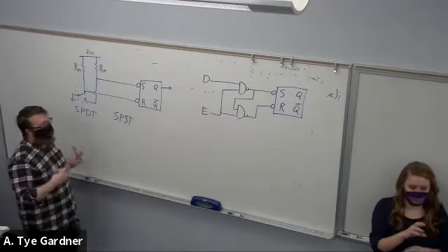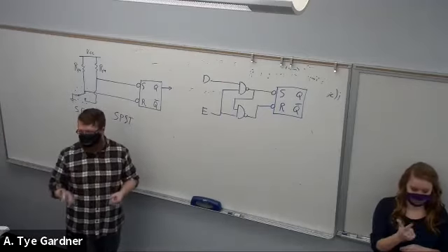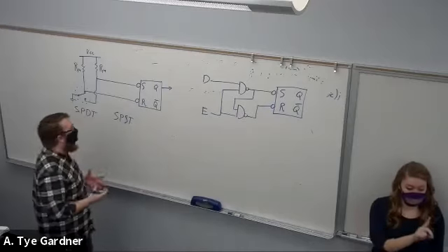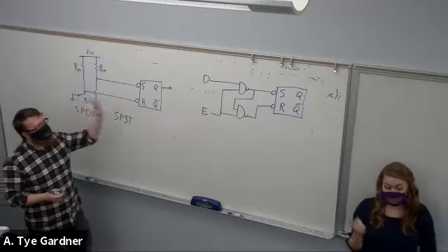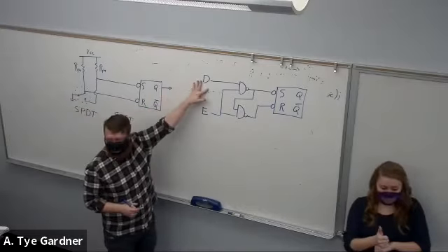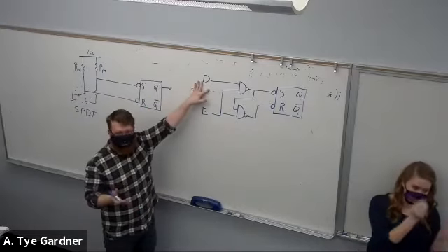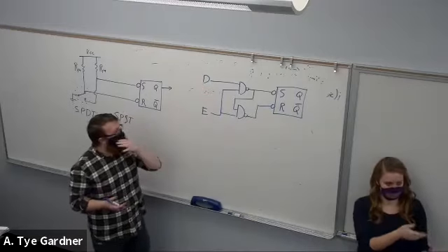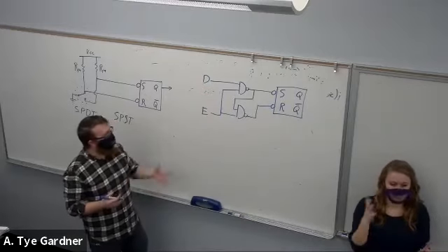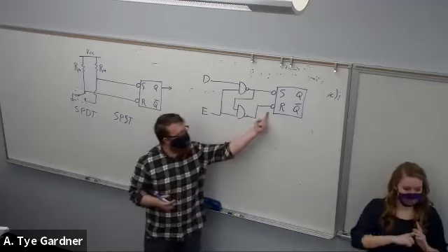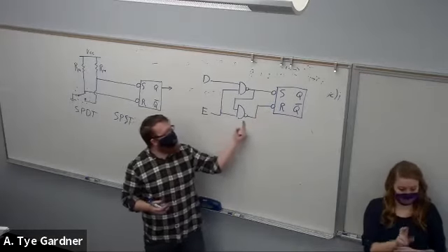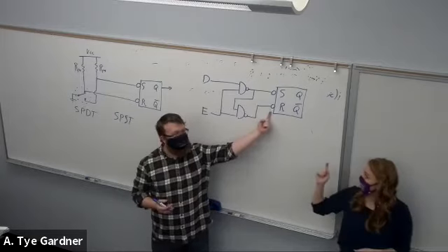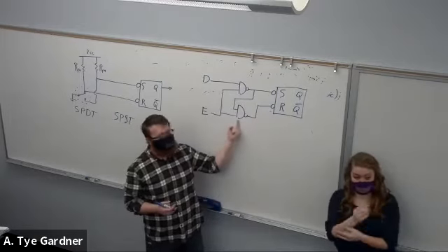So this is what we call a D-latch or data latch. So rather than having the options to set or reset, we can actually take a data stream, D, and save that. Now, it's kind of easy. This is why I did the inverting inputs for set and reset, because you can see that this NAND gate and this inversion is equivalent to drawing AND gates here.